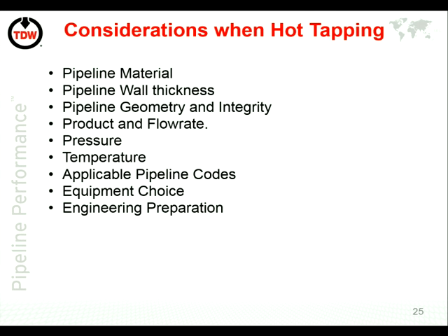Saudi Aramco is very unique. They have a huge storage facility of fittings, but all of those fittings are to a Saudi Aramco code. They're not to anybody else's code in the world. Slight variation. If you put them all side by side, you wouldn't know the difference, but the way they've been made, the preparation, and the welding procedures that have to be followed are specific to them.